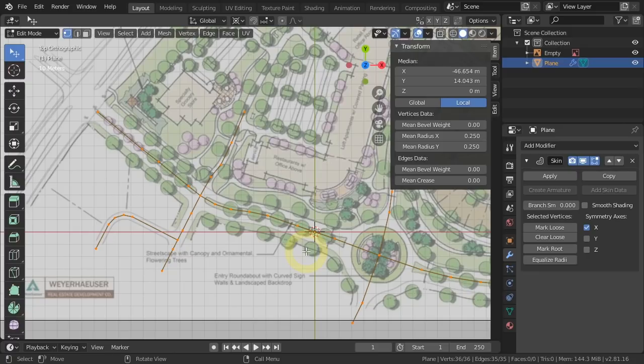For the starting road width, we already know that this main road width is 17 meters or 8.5 meters radius. So let's start with that number. Click drag like so to select both of the input fields. Then type 8.5, then enter.